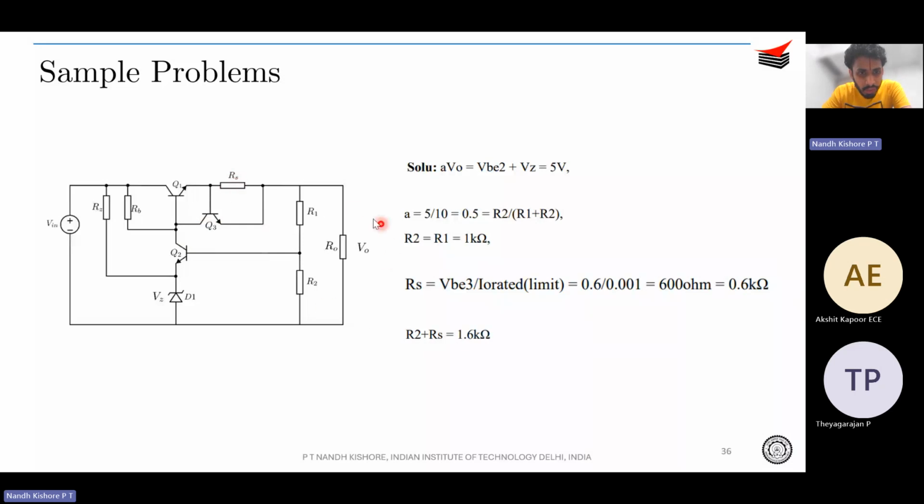That is the current limiting circuit. You understood, right? So one was just KVL in this loop to get R2, and the other one was the current limiting circuit. That is VBE is equal to I0 into RS. Okay. Just go through this for a moment, and in a minute, we will switch on to the next question. Again, a very simple problem, right? Just calculate what is R2 and RS. Just apply KVL, you get the answer.